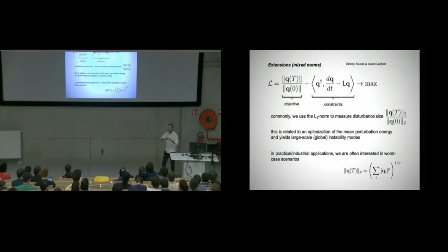Usually energy is linked with shear. Just by displacing shear, you can actually create energy. So if you have an optimization and there is a big shear layer that goes really long, like a separation bubble, you're going to get a structure that spans the entire separation bubble, okay? Because since you maximize energy, it really takes every little bit and piece that is available from the flow to create as much energy as it can, okay?